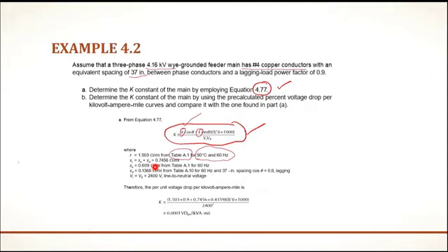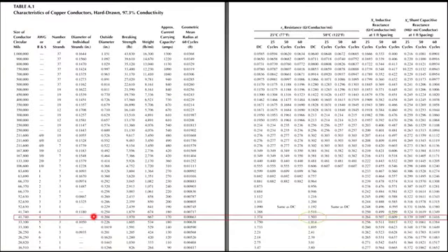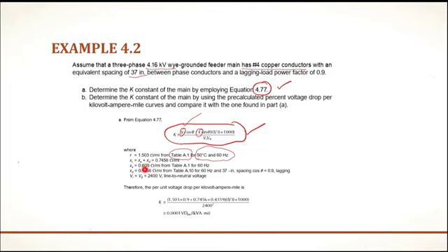So I'm just going to use the tables in order to see what is the value of XA and what is the value of XT. In order to see what is the value of XA, again we are going to use appendix A.1 table. We are going to use the same row, that is for 4 size conductor, and for 60 Hz frequency, this is the value of XA, that is inductive reactance at 1 foot spacing. So this value is 0.609. You can see this is 0.609.